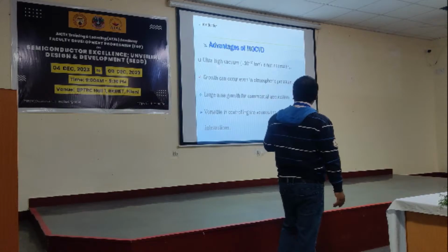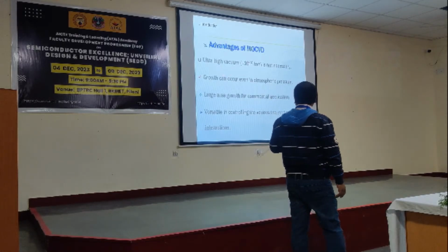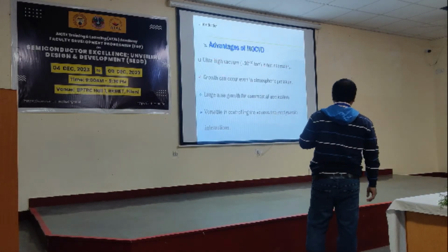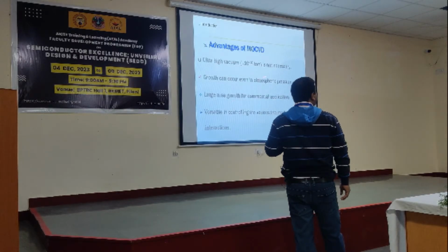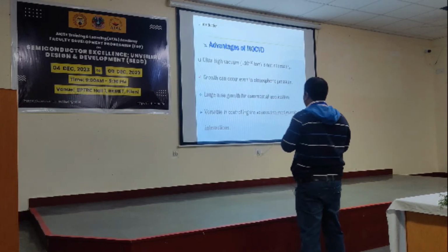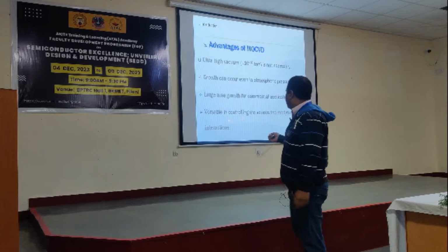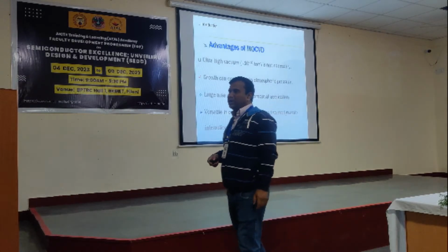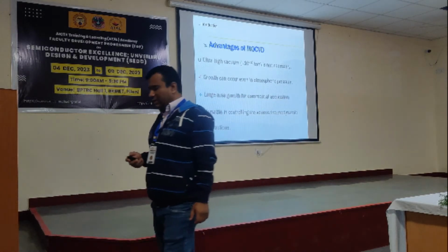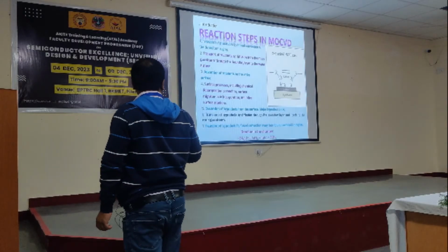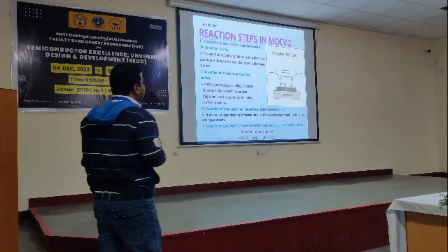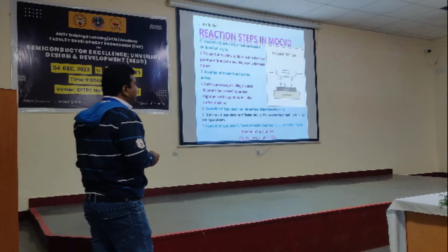Several other advantages are there. An ultra high vacuum is not necessary, you can also grow the material even at atmospheric pressure, and it also facilitates very large area coverage, and you can control the various thermodynamic reactions in a very suitable manner. Now, what is the typical reaction process? What is involved in the MOCVD?